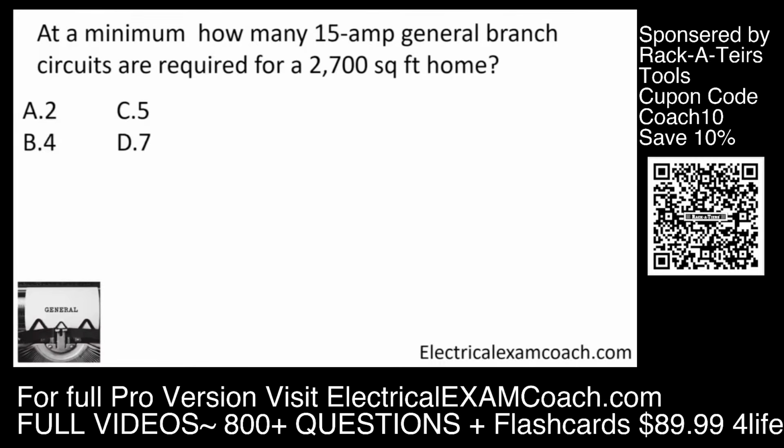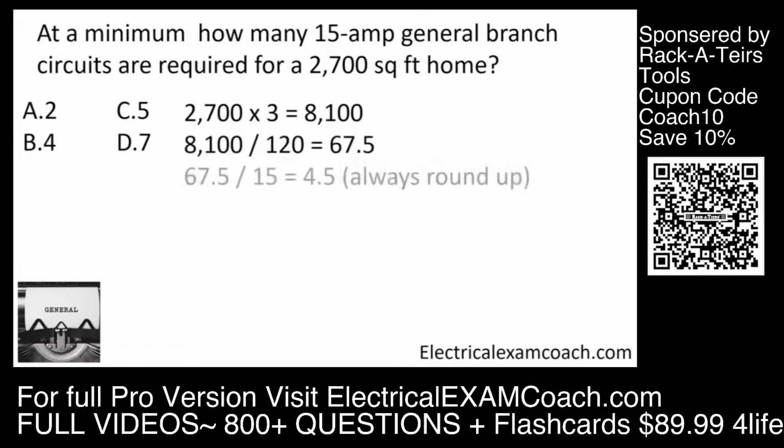At a minimum, how many 15 amp general branch circuits are required for a 2,700 square foot home? The first thing we're going to do is take our 2,700 and multiply it by 3 VAs per square foot. Then we're going to take that and divide it by 120, which is our circuit voltage. Then we take that remainder there and divide it by the size circuit, and in this case, it's 15 amps. It's going to equal 4.5, and we're going to always round up to 5.